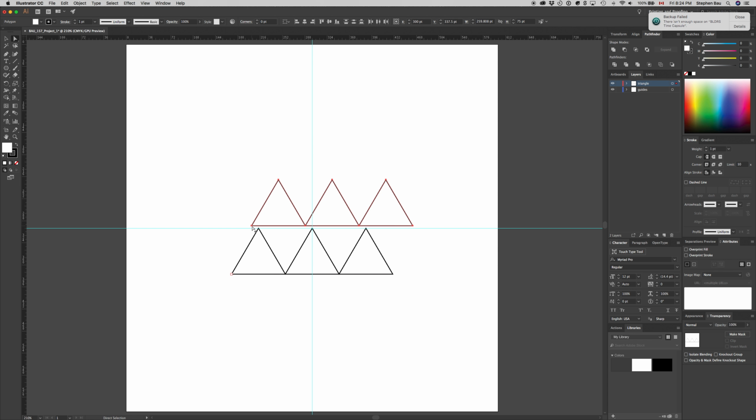Haha, that didn't work. So I'm going to Command Z undo. Somehow I chose all 3 of these objects. I only want Shift, Option, click and drag, and now click and then drag with the Option key selected and let go when I snap to point.